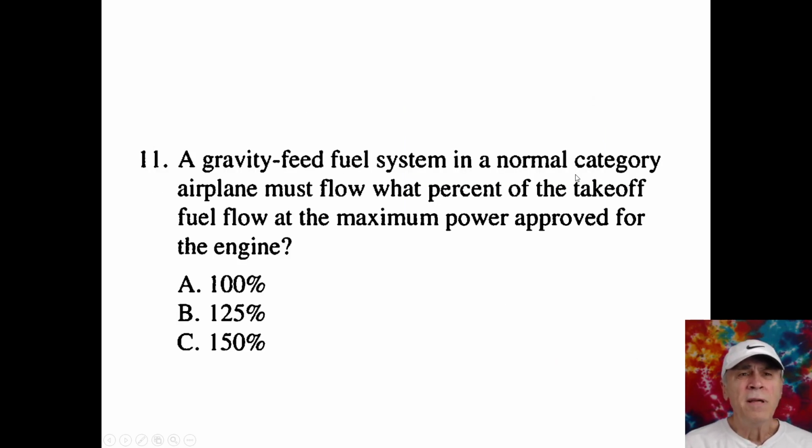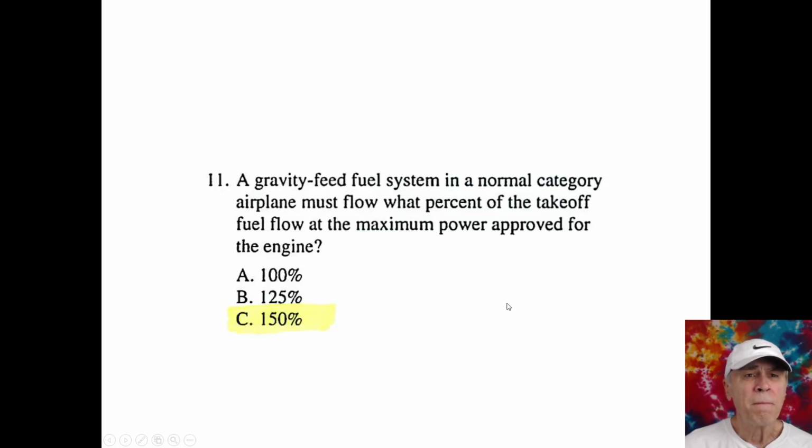A gravity feed fuel system in the normal category airplane must flow what percentage of the takeoff fuel flow to the maximum power approved for the engine? Gravity fed was 150%. Do we have the same question for the other ones? What is the requirement for a pump fed system? 125. What about for a turbine? 100.